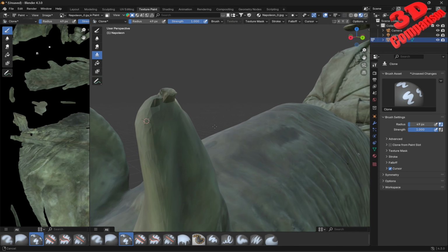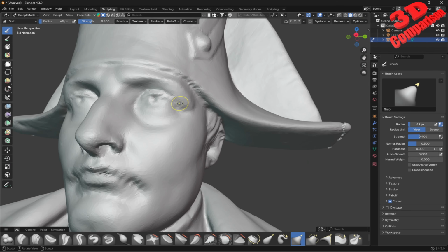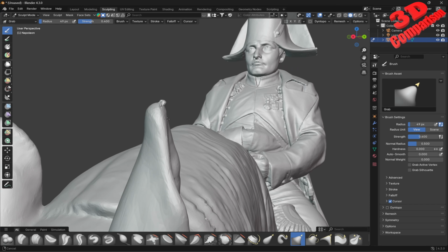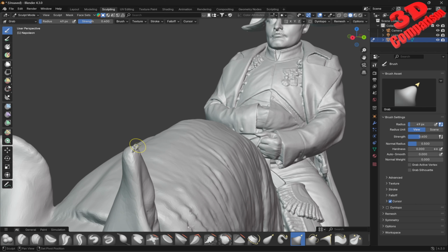But in this case, I consider this to be added geometry, so I will go within the sculpting environment, not modeling. This will take a little bit of time to pass between those workbenches since the model is quite large, but I will go again to sculpting. And I know that we have some added geometry over here, and that's visible. So I'll just hold down Shift.